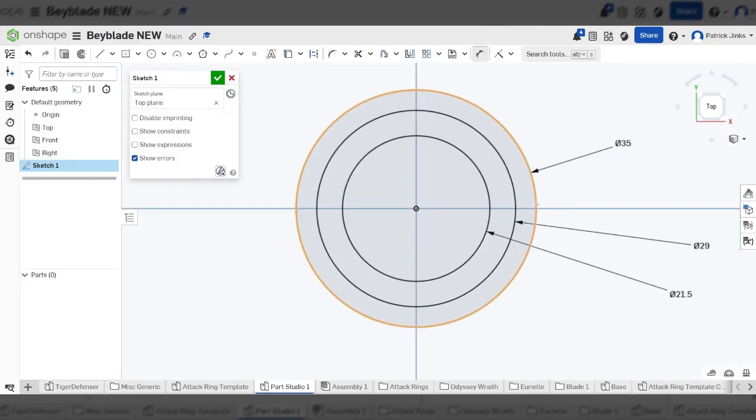And now we're going to make some construction lines. Construction lines are things we use to make intersections. What that means is we can cut away different parts of these circles and leave just the arcs that we want to remain active. So I'm going to get my line tool. I'm going to start off on the bottom left quadrant on the middle circle.